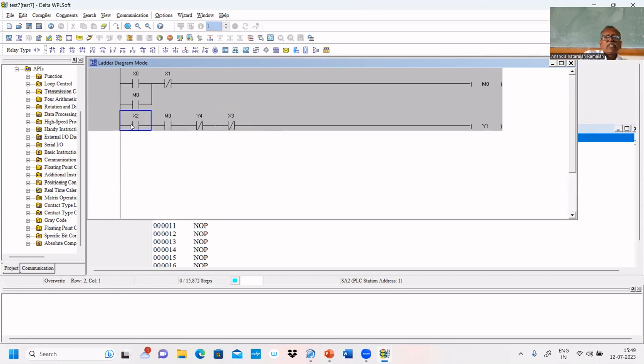But this X2 will not work after some time, because if you start filling, the proximity switch will first be submerged inside the liquid. That's why it will not give 1 after some time. It's not empty.